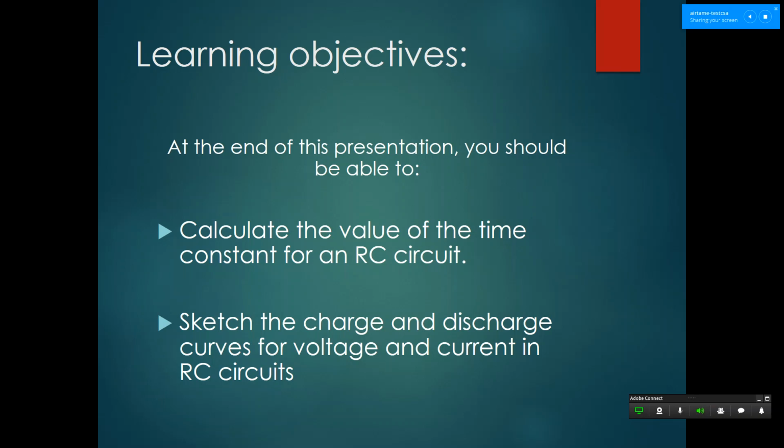And the way they charge and discharge, it used to be that when we just had capacitors wired to a battery, that we would consider the charging process to happen instantaneously. I mean, obviously in reality, it's not instantaneously, but for all practical purposes, it's instantaneous. But now if you put a resistor in front of a capacitor, then the charging of it is not instantaneous, all right? So it happens gradually, similar to how an isotope might degrade, right? Same kind of curves. And then they'll discharge, and then the discharge also doesn't happen instantaneously. It happens over time.